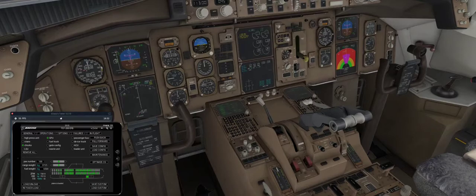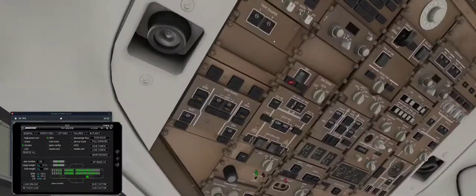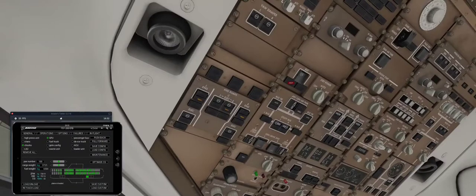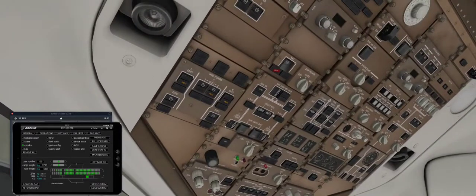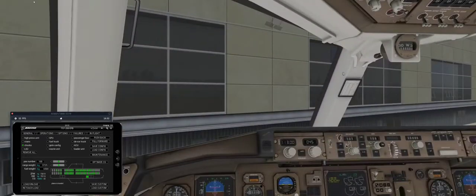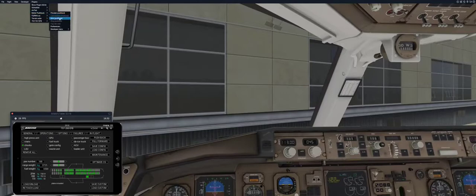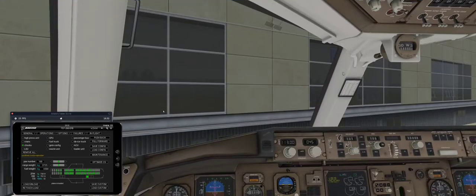Looks like we're at 99. We're on APU. We can lose ground power. Don't forget to actually transfer off of ground power before you remove the ground power truck or you will ruin your ground power receptacle. And we're on APU. We should tell our guy we're ready for the pushback, right? Ground to cockpit, tow is driving up.